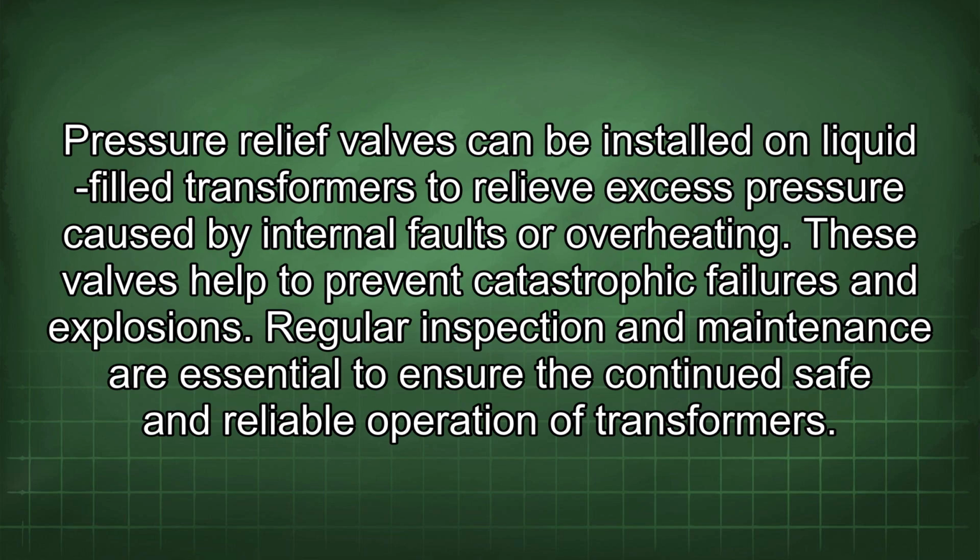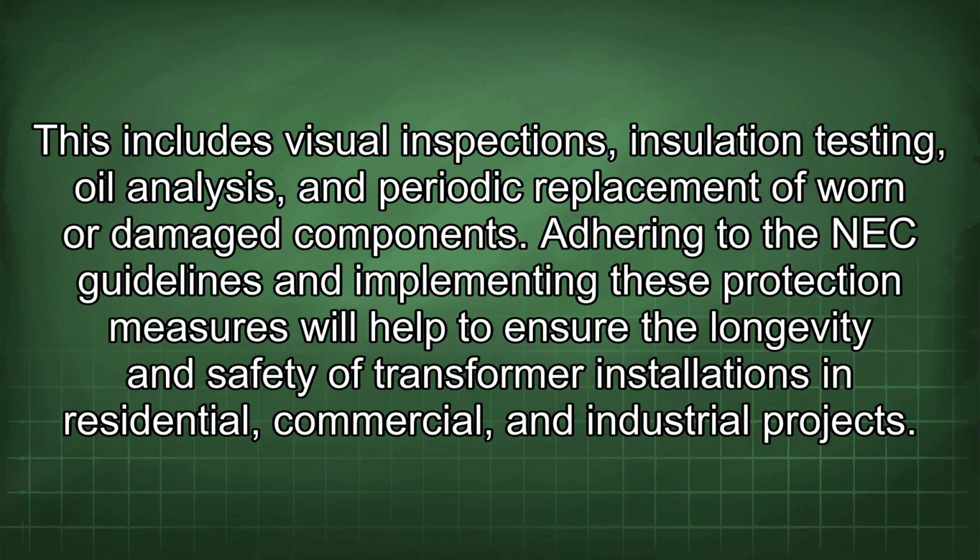Regular inspection and maintenance are essential to ensure the continued safe and reliable operation of transformers. This includes visual inspections, insulation testing, oil analysis, and periodic replacement of worn or damaged components. Adhering to the NEC guidelines and implementing these protection measures will help to ensure the longevity and safety of transformer installations in residential, commercial, and industrial projects.